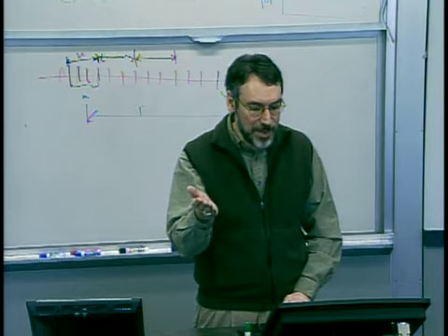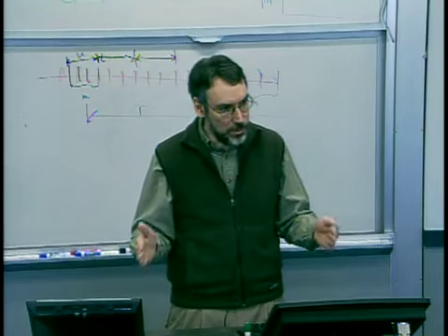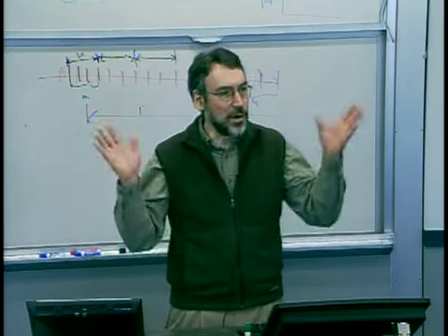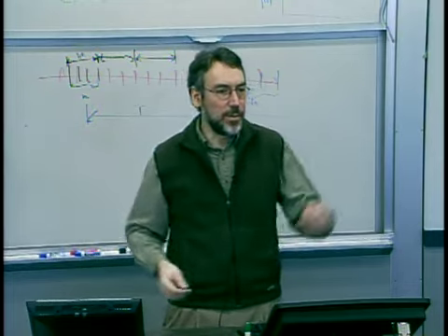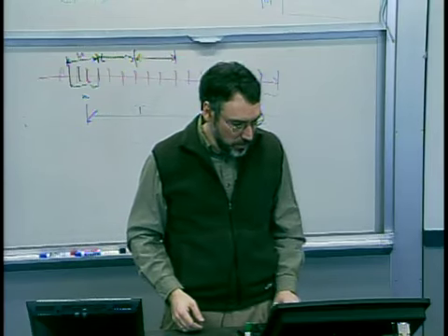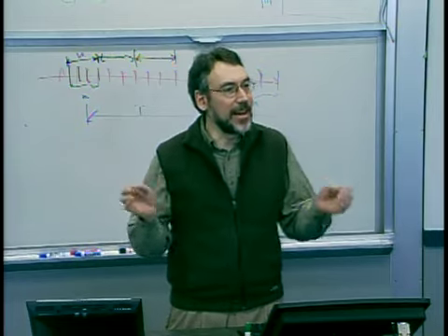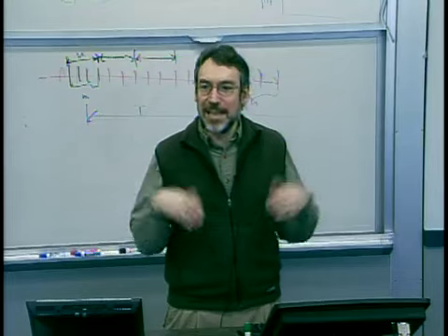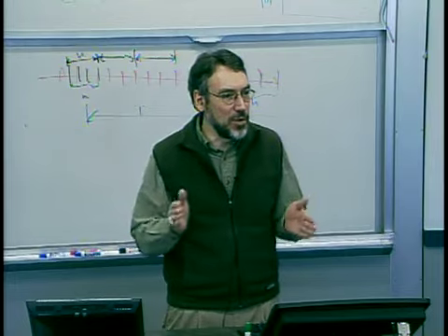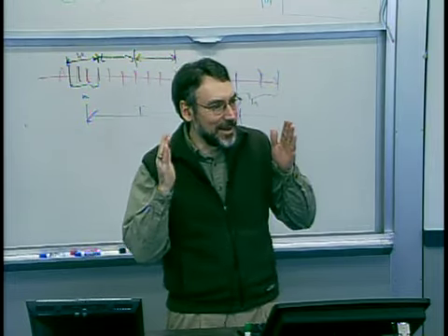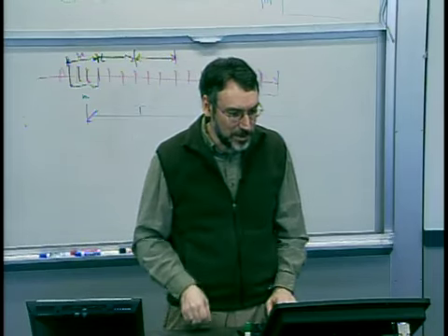And then we have an upper spec limit and a lower spec limit, and we simply say, as long as the part dimension is within that range, we're going to call it a good part. And it meets maybe the design requirements, it meets our consumers' requirements, what have you. What we're saying is, in essence, anything within those spec limits is equally good and equally shippable, right? So there's no notion of better or worse, it's simply an on-off decision, acceptable or not, okay? So that's a spec limit.